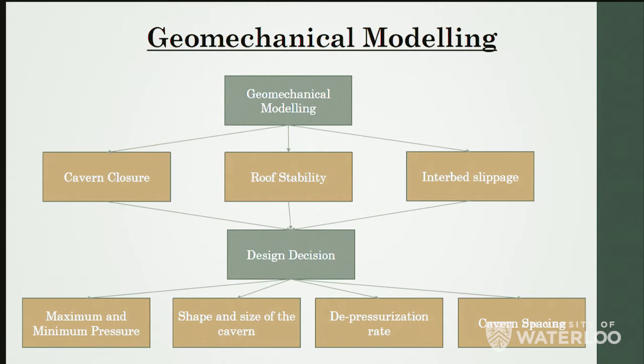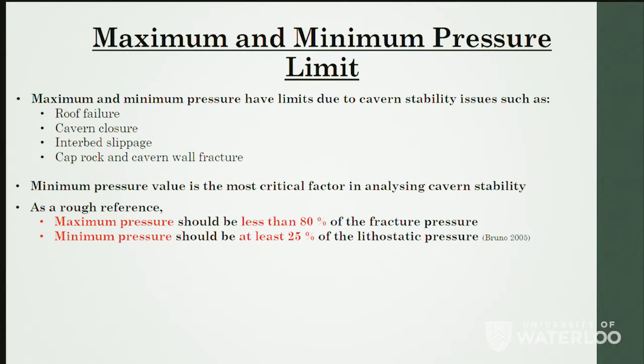Well, let's talk a bit about maximum and minimum pressure limits. As a cavern operator, during the injection period, I would want to operate the cavern at maximum pressure to get in as much air as possible. And during extraction, I would try to operate the cavern at minimum pressure so that I can extract the air for a longer time and produce energy for a longer time. However, maximum and minimum pressure have limits, and these are due to cavern stability issues.